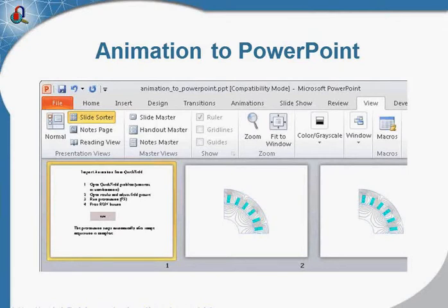For transient problems, the field picture is copied from each time step, and for time harmonic problems, the field picture is copied every 10 phase degrees in the range from 0 to 360 degrees. And each picture is inserted into a separate slide of the presentation.